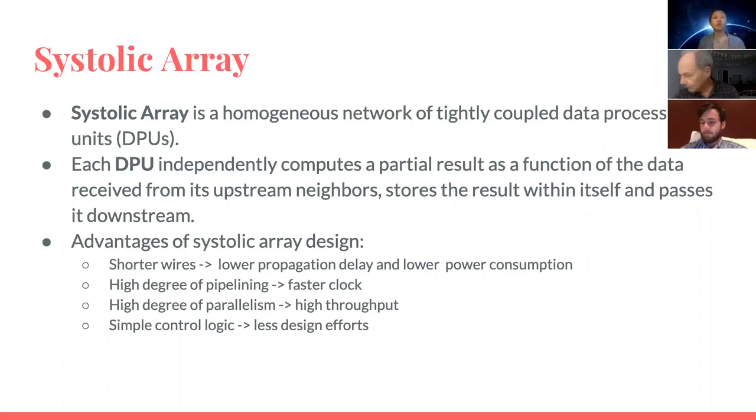But also the control logic is very simple, because it's simply dependent on how the connections of the systolic array are, right? So there's no control to essentially determine which DPUs each of the data is going to, because you just feed it into the peripheral ports of the whole PE arrays, like the DPU arrays. And pretty much the execution of this workflow will be determined by the data flow on this hardware. So there's no extra control logic needed.